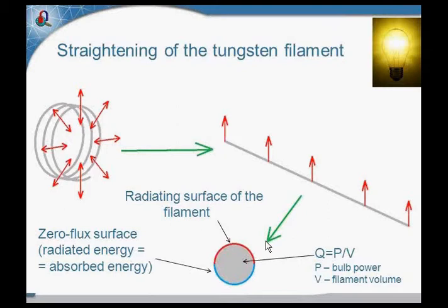And as heat sources, we set volume power of the lamp here. We have the bulb power. In our case, it's 100 watts, and we divide it by the filament volume, and we get the volume power.